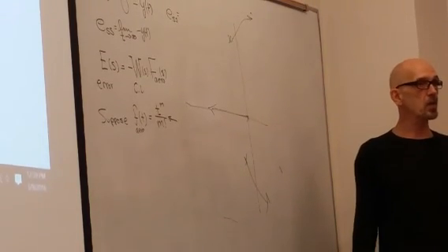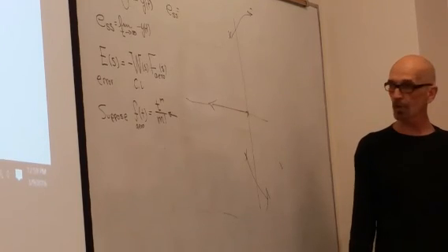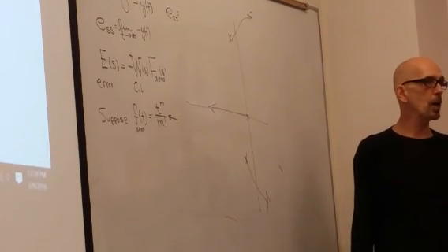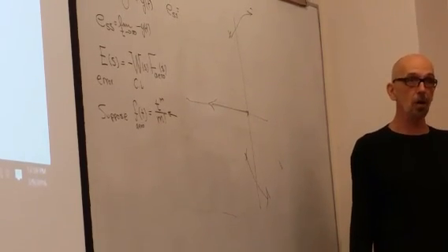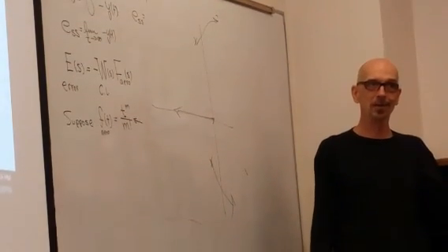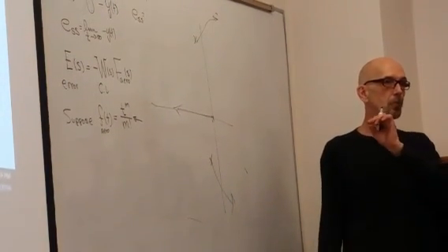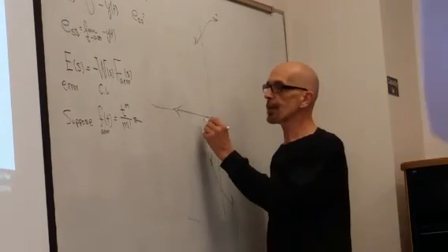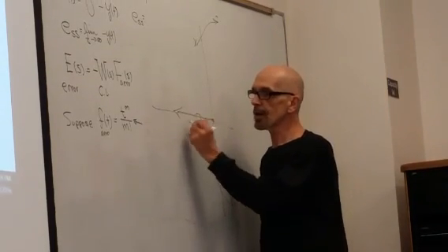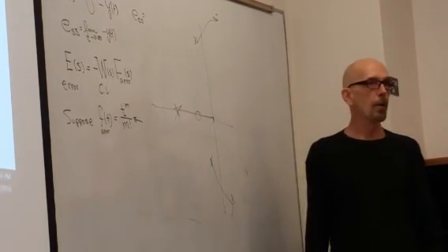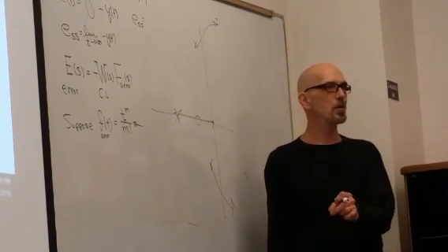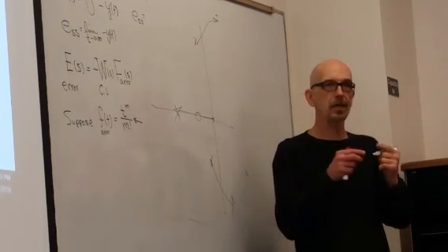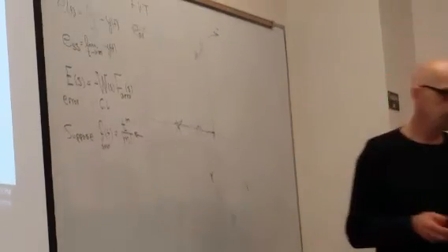So what we're going to do, and we did this already in the root locus domain, we're going to put a pole zero pair in there. We're going to design a lead controller, but in the frequency domain. You already did this problem in the root locus domain. Next class, I'll say, let's put a zero here and let's put a pole here. But we're going to do it via frequency domain design, not angle criterion in the root locus.